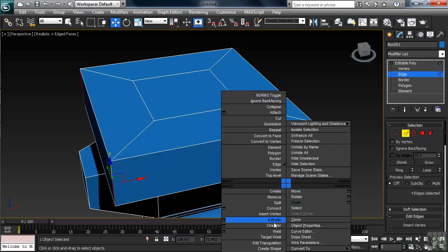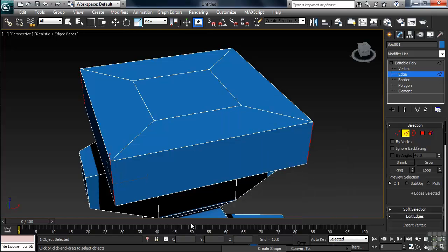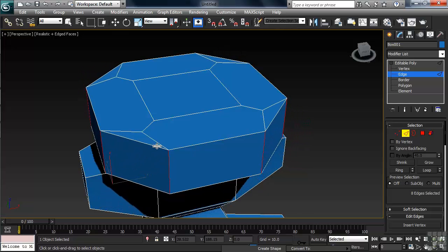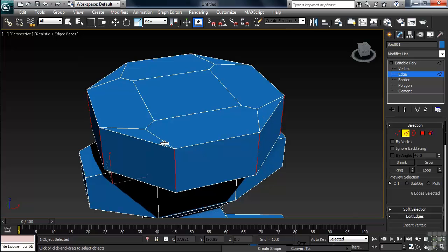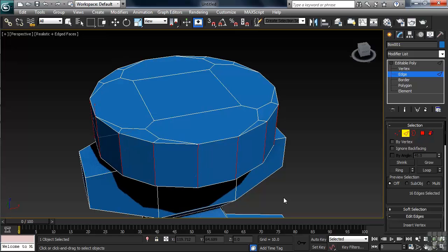It's going to be located on the lower left-hand square directly below Extrude. Now chamfering an edge will divide the edge in two. Go ahead and make all the polygons that go around the sides right about the same size. Commit to the chamfer by letting go your left mouse button, then chamfer again. All we're really trying to do here is round off the top section.